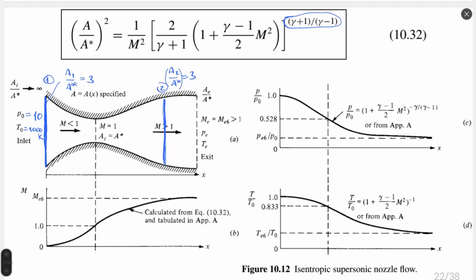So I define pressure, I define temperature, I define area ratio on entrance, I define area ratio in the middle, in supersonic section, and I would like to calculate starting from Mach number, okay? Because area will tell us what is Mach number at these 2 points.